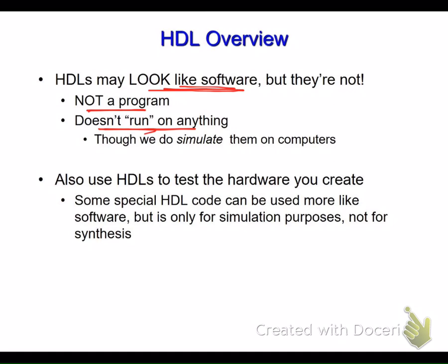As I mentioned here, some special HDL code can be used more like software, but this can be only for simulation purposes, not for synthesis. In another sense, you can think of a test bench, something that you write for simulation purposes. You don't have to have your test bench synthesizable, meaning that for the code that you write in a test bench, you don't need to think about whether it can be downloaded over the hardware or not, because you will not download that over the hardware.